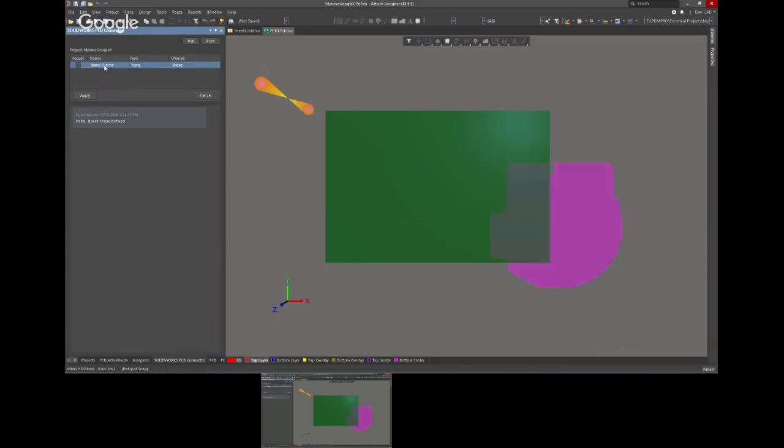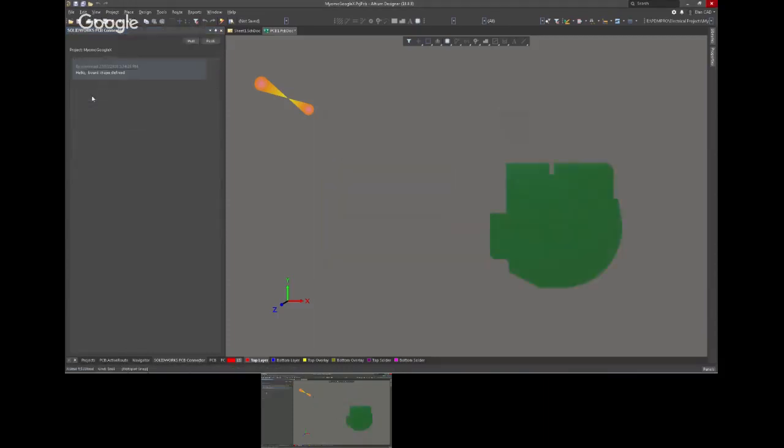Wow, I get a magenta color flashing that newly proposed board shape, the board shape. I'm not talking an outline. I'm talking the board shape. I'm going to go ahead and accept. Bam, it redefines my board shape. Back to the 2D mode.